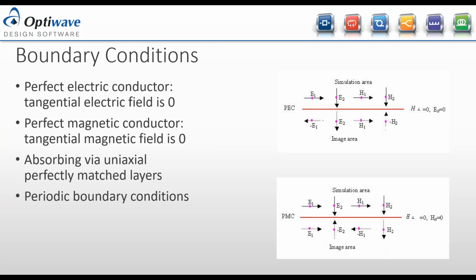You can think about it as stretching the coordinate through a complex space, which is sort of strange to think about. I like to think about it as this engineered material that you can, it's not very real and you can't actually, well maybe you can create it, but we can't create it presently. It's some fictitious material that allows you to match the sort of impedance of your simulation domain, and it won't create any reflections. However, once a wave enters this material, it'll start to be absorbed quite quickly.